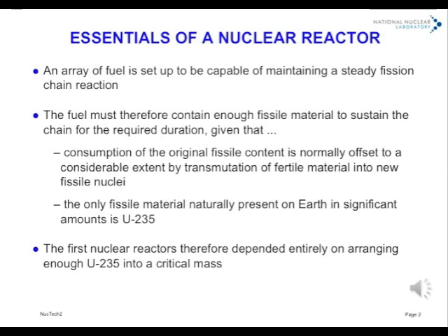Unlike a system based on chemical combustion, where fuel is added and combustion products, including any ash, removed continuously, the fuel stays in the reactor for typically 3 years or so, and only heat is removed. The fissile content must therefore not only be adequate for the initial startup, but must be maintained for a very considerable period.